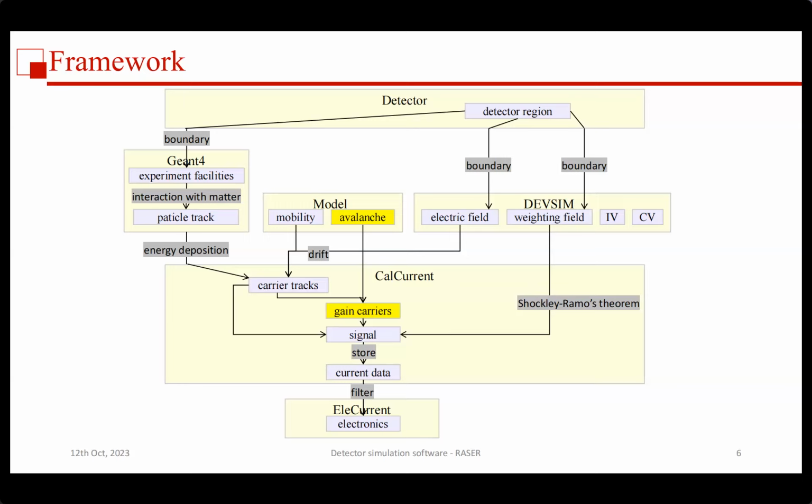The process of solving the electric field is complemented by creating a mesh, defining the doping, and incorporating models such as the Shockley-Read-Hall model and the Hatakeyama avalanche model. In DEVSIM, equations are transformed into integral forms and solved. And also you can simulate IV-CV information here.